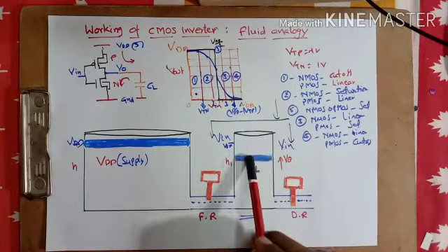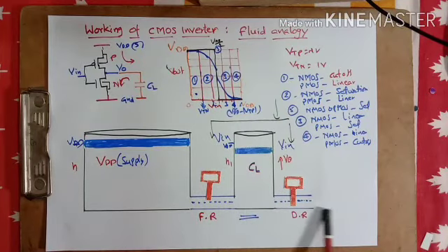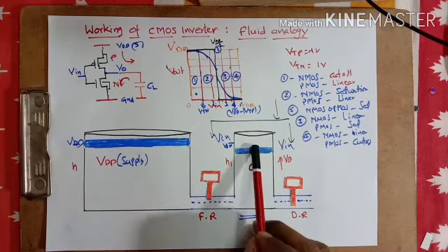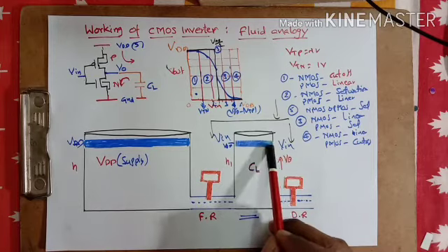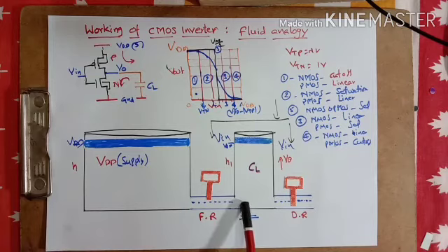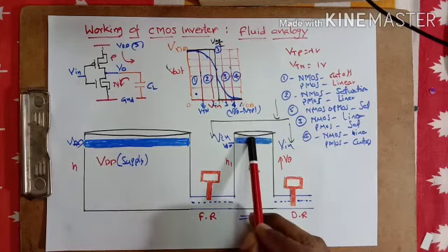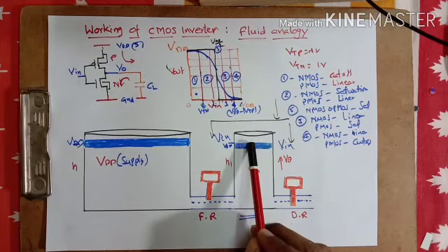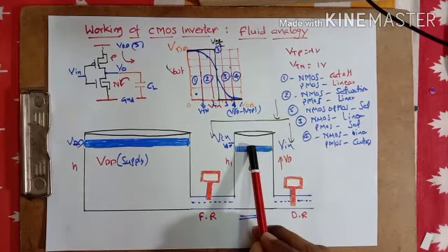So even though height is changing, the rate of flow, the draining flow does not change. This is not changing actually. DR, draining rate, does not change. Only the filling rate will change. Now as we see, because it is opened more, it is having the tendency to fill with more water, but only less water is going out. So that the more water filling now has to be changed by the level here, such that